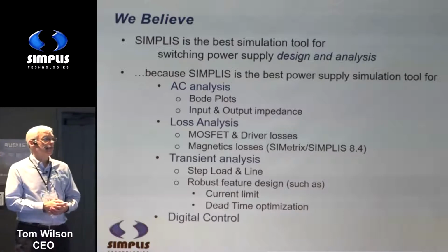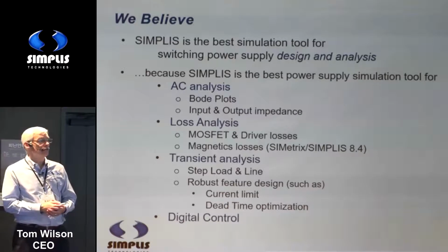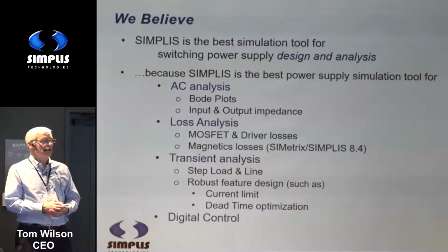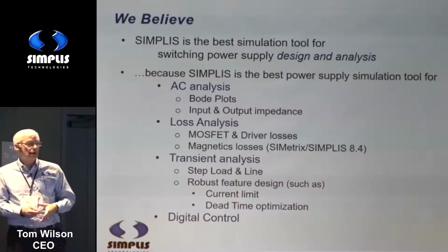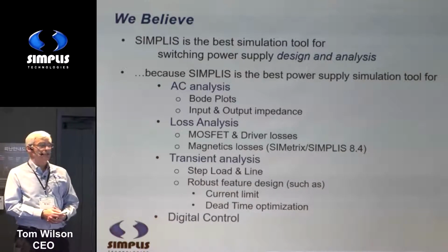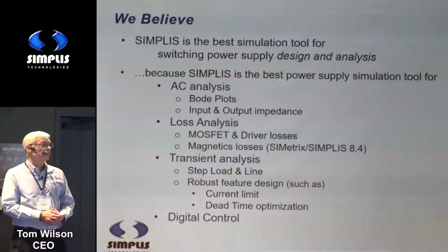And the reason is because SIMPLIS is the best power supply simulation tool for AC analysis, including Bode plots and things like input and output impedance, and then also for loss analysis, looking at switching losses in MOSFET and the MOSFET drivers. And now, as of version 8.4, we do a really good job with magnetic losses, and we'll show you a very brief demonstration of that today.